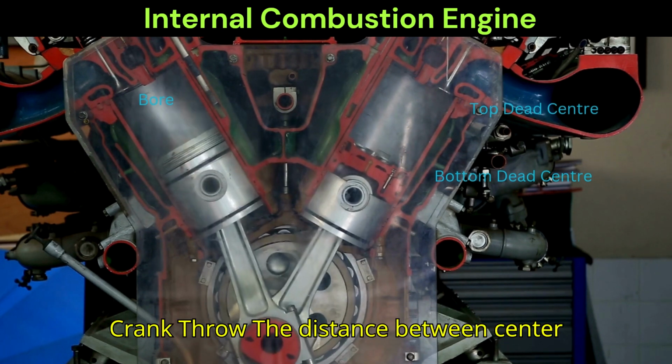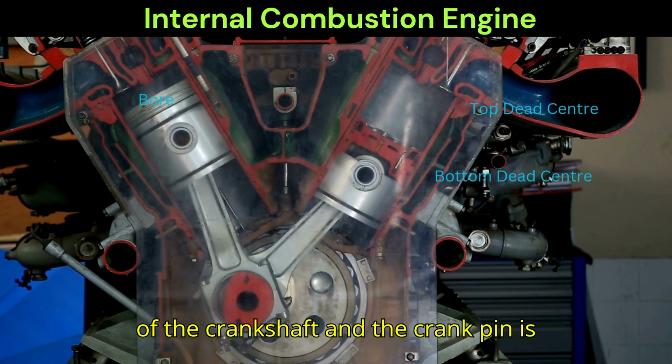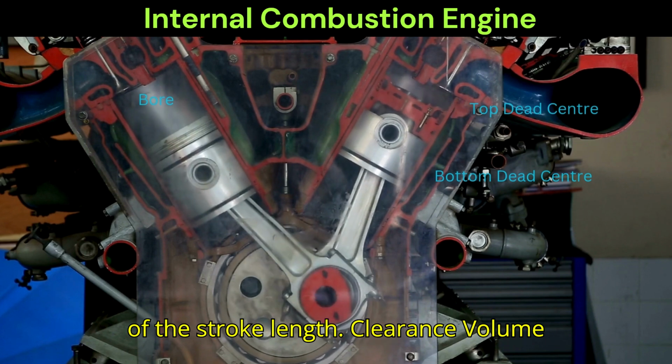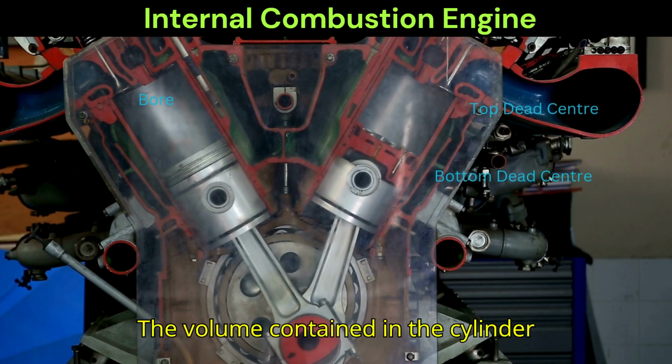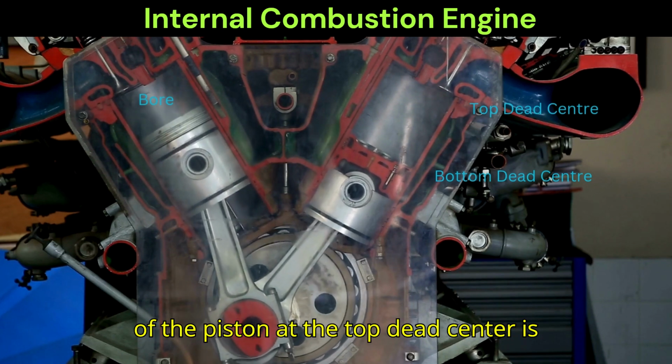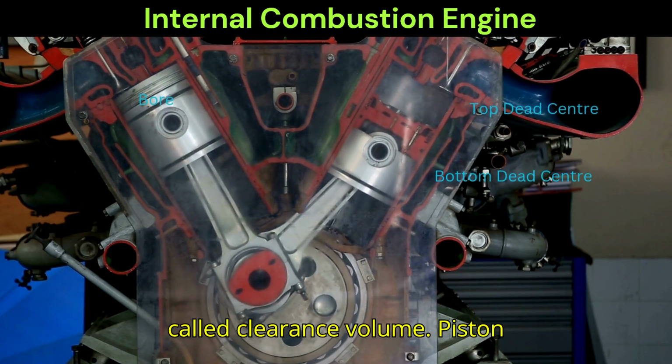Crank throw. The distance between the center of the crankshaft and the crank pin is called crank throw. It is equal to half of the stroke length. Clearance volume. The volume contained in the cylinder below the cylinder head and above the top of the piston at the top dead center is called clearance volume.